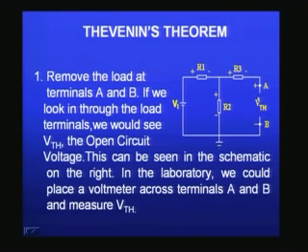It is an open circuit now because the circuit is open at this point, you have removed RL. So the circuit is open, that means infinite resistance here, and if you measure using a digital multimeter the voltage between the points A and B, that gives the effective Thevenin's voltage appearing at the output.